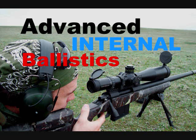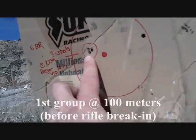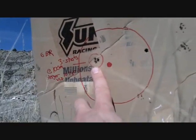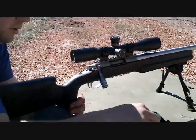So if you have a stock that's giving you problems, you probably do want to replace it or have it glass bedded. That will usually fix it. You probably want to have your barrel free floated, if that's giving you any problems. And the way you can test this usually is just to go out and start shooting for groups. That'll give you a pretty good indication of whether or not you're having harmonic and vibratory inconsistencies. If you can go out and consistently shoot half-inch groups all day long, half minute of angle, you don't have any harmonic or vibratory inconsistencies that are going to throw you off. So that's the test there.